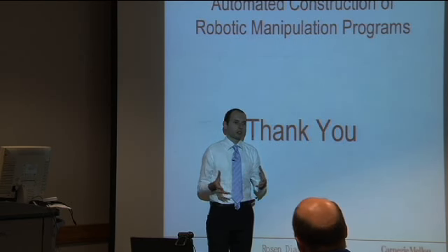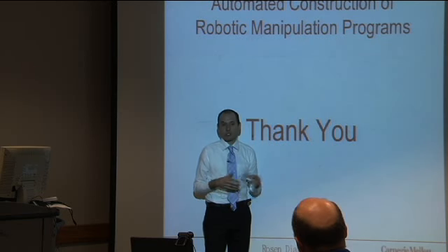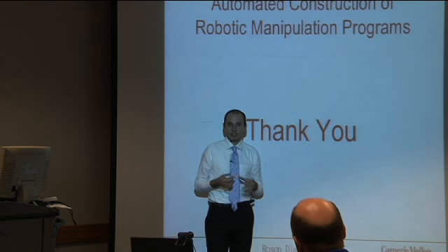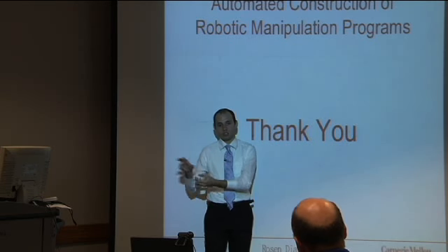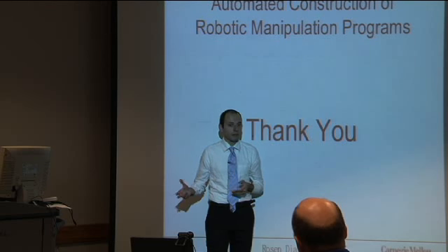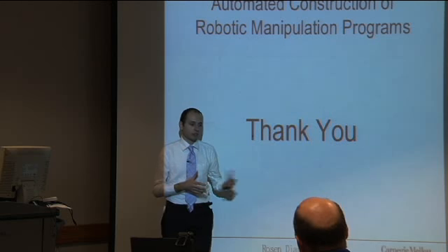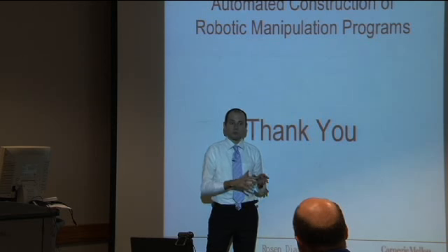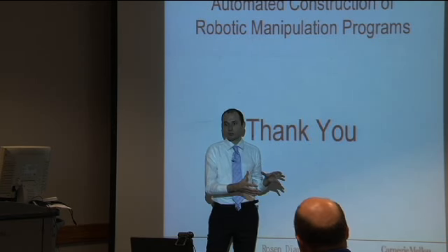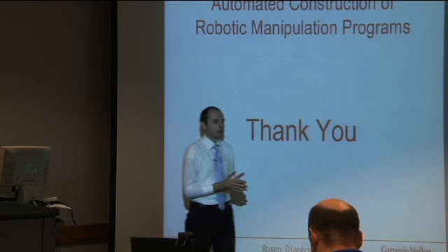in some sense, the repeatability measure captures the essence of what a fragile grasp is, which means that the grasp cannot achieve a particular orientation or position with respect to the object. It slips, or it can easily slip. By computing these standard deviations, we have shown that we can reject all the fragile grasps while still maintaining about 50% of the stable grasps. And we discuss various trade-offs in the thesis.